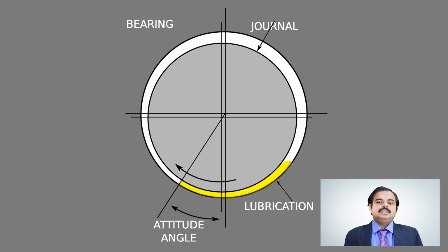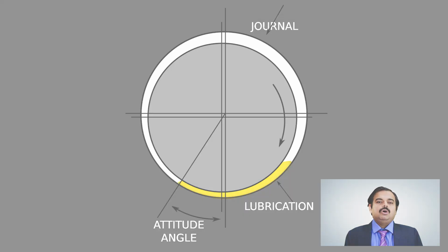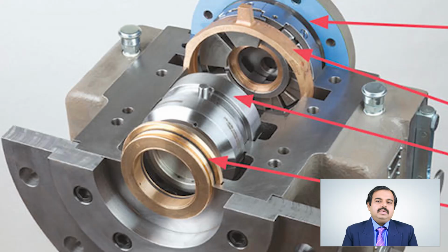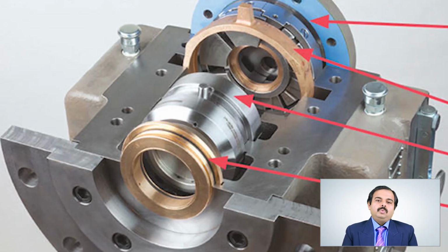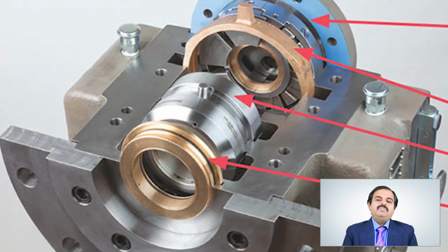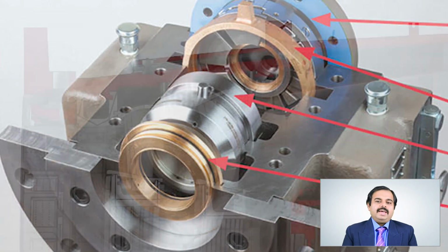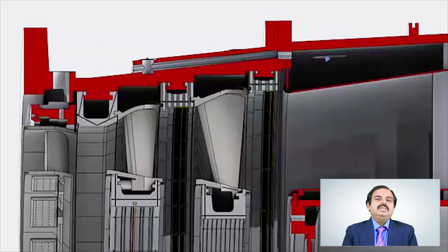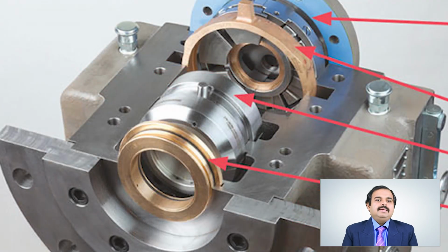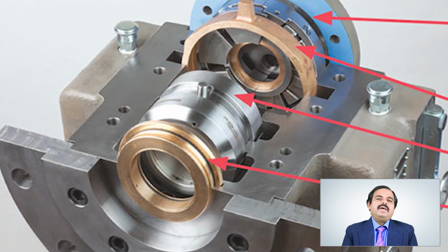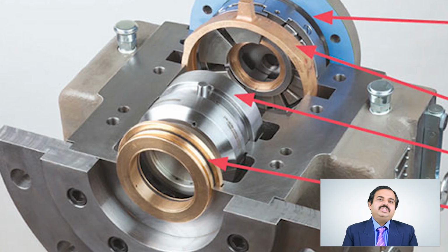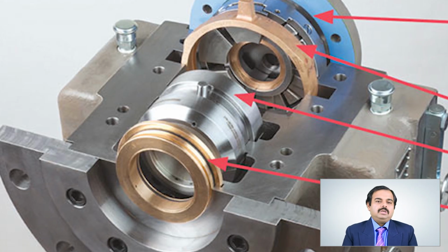Under emergency, that is, in the case of power plant AC supply failure, lube oil can be supplied by a DC oil pump before the turbine is turned or barred. The turbine oil is also used to lubricate the bearings of the generator, which also seals the hydrogen gas which is used for cooling the generator. The turbine oil also carries away some of the heat generated at the bearings.